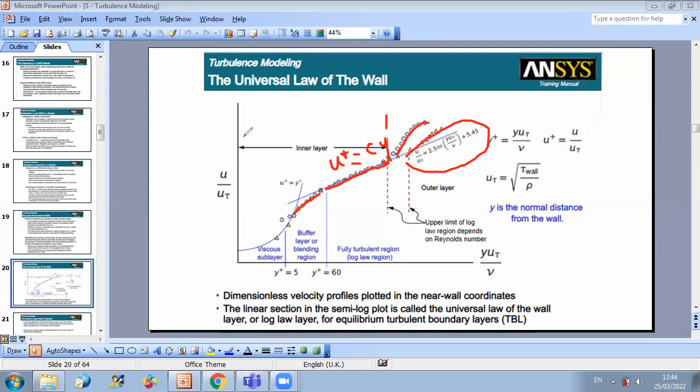This is why, if you remember, when we were discussing in the CFD lab the different options in ANSYS Fluent, if you go back to the turbulence window and select k-epsilon, for example, below it you can select the option of enhanced wall treatment. Whenever you select enhanced wall treatment, ANSYS will implement all of these models to take into account the effect of flow development near the wall.